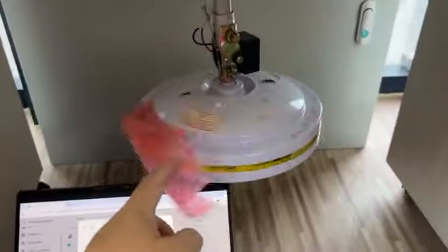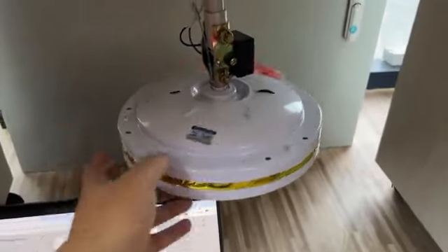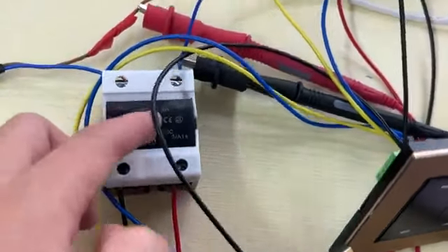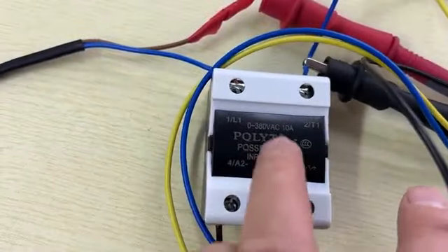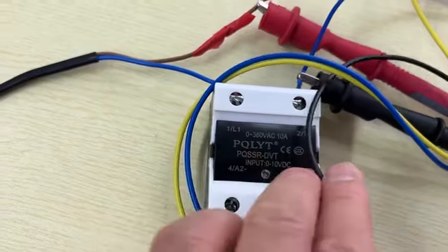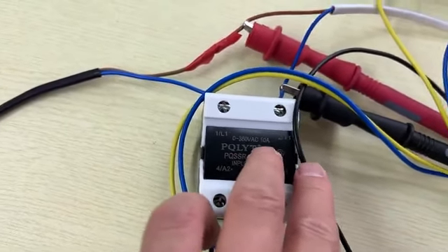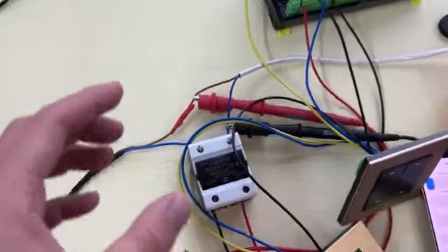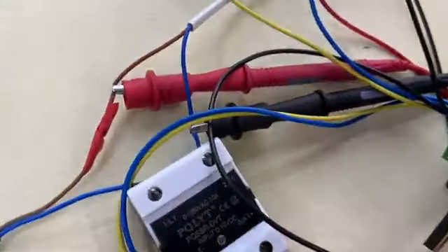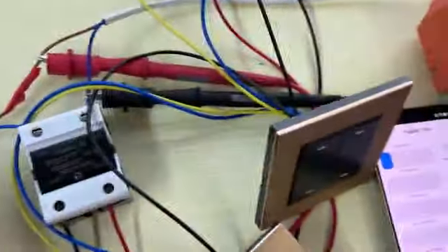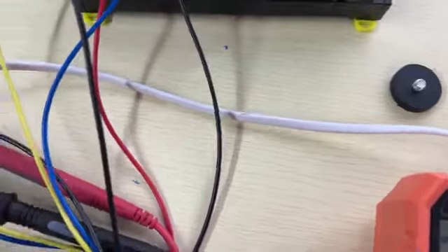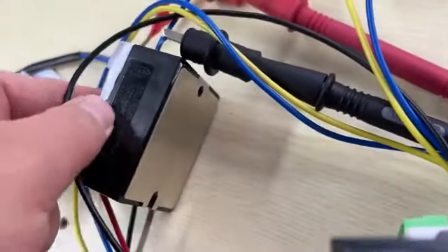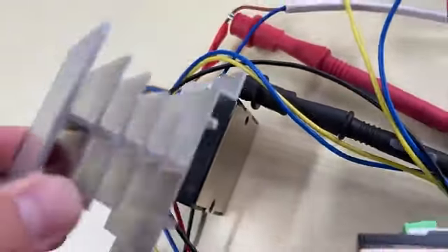And if you want to control a different motor, if you want to control a very large current motor, you just need to replace this SSR. And this one you can see is 10 ampere, and you can also choose some different ampere, such as 40 ampere, 60 ampere, some big ampere. If the SSR is big, because the current is big, you need to install this heat sink. So you can see at the back that can connect with this heat sink.